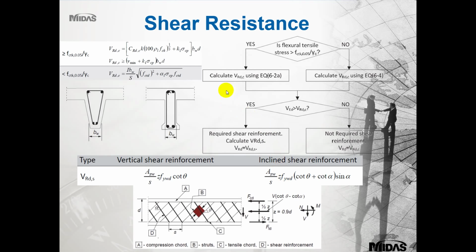So now we're just going to look at the shear resistance. What I just want to say is the software checks for the tensile stress as it is the governing stress for shear, which is the occurrence in the beam. I'm just going to hover over that. From the diagram we can see the strut tie action in the concrete beam with the stirrups, just illustrating that with the red block.